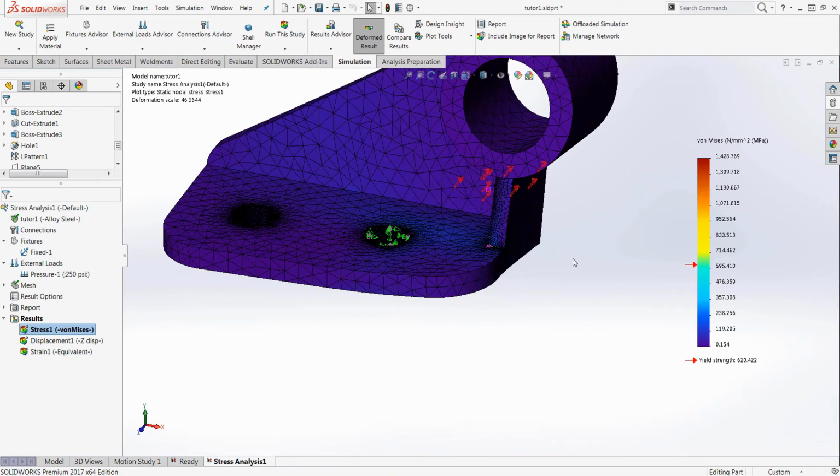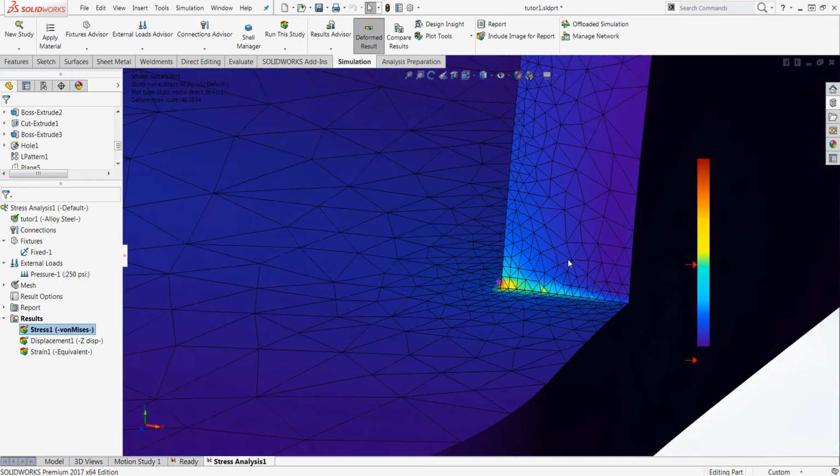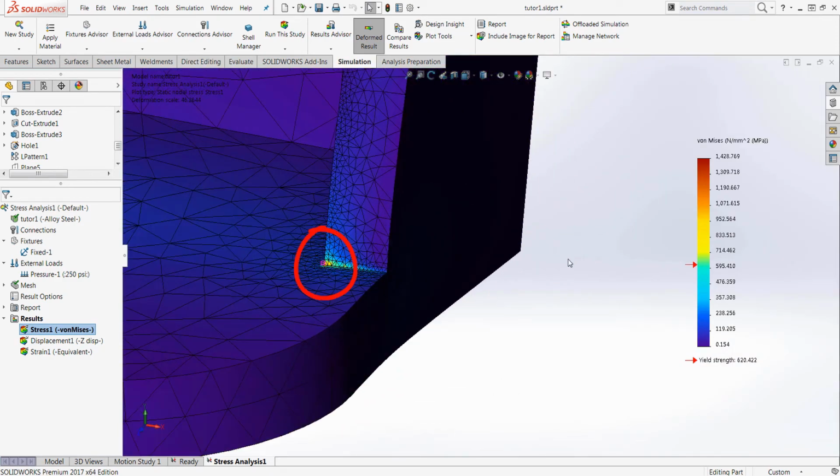Once the run is complete, you will again notice the stress values rise, but are concentrated at the point where the three edges meet. Now, unless the component is being fatigued or is susceptible to corrosion around this area, the design can be regarded safe. Once again, the stresses around the concentration point still remain around 210 megapascals, like our previous two attempts.